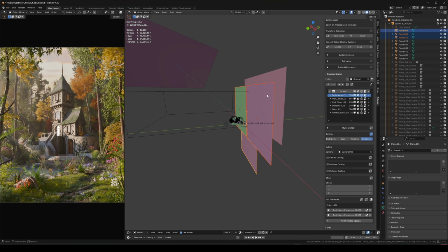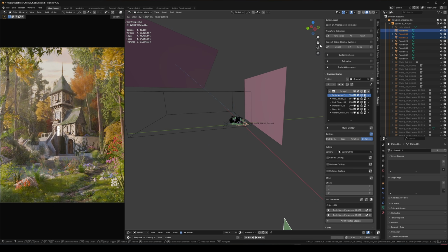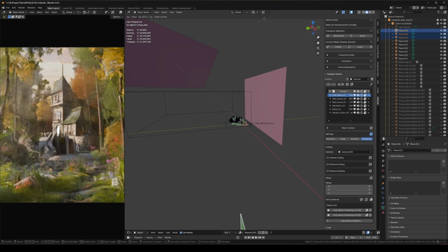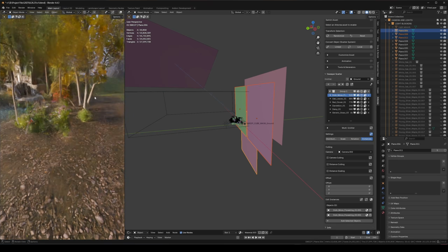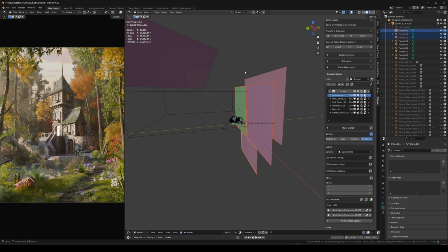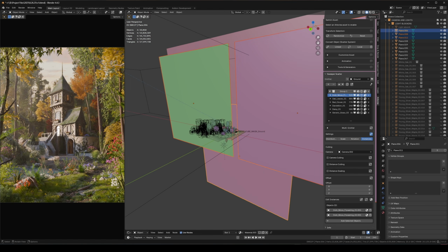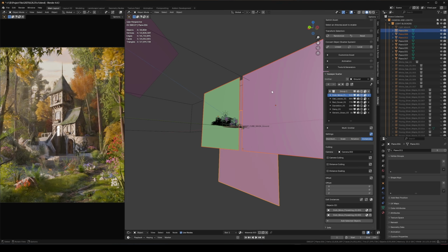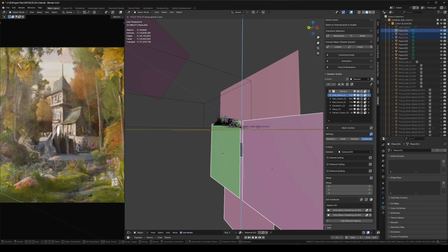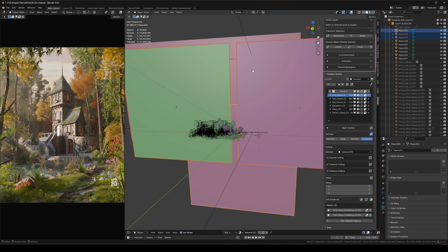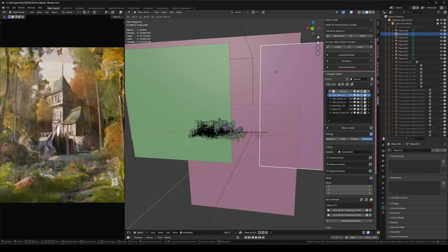Okay, so for these planes, with them and then without them, you can see on the right side it darkens the shadows a bit and makes it a little bit less flat. The reason for this is, as I mentioned before, there's a lot of ambient light coming from this HDRI. These being directly on the right side and massive in general is blocking all of that ambient light coming from the right side, but still allowing it to come from the left side, above it, backside, and so on. So basically what I did was create these planes, started moving them up until I got the contrast that I liked.